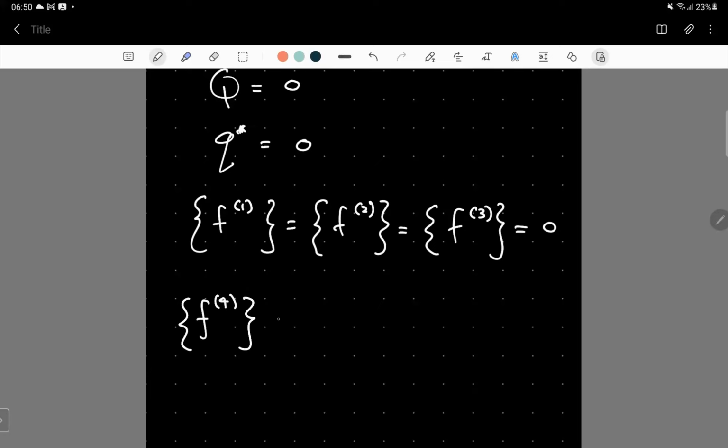There will be convective heat transfer from the free end. So we have an equivalent force element, which is the convective heat transfer coefficient times the free end temperature times the area, multiplied by this column vector.